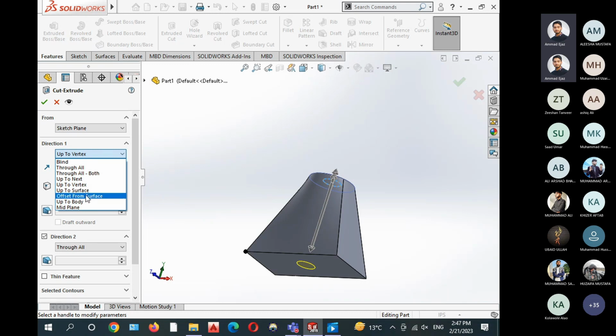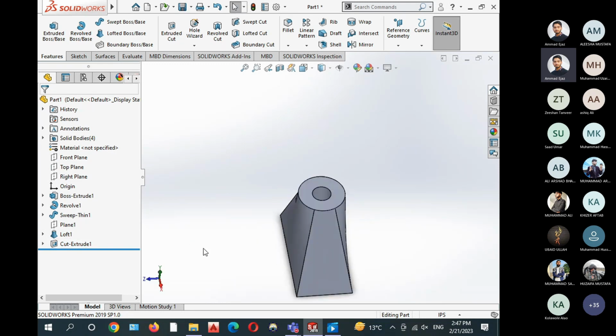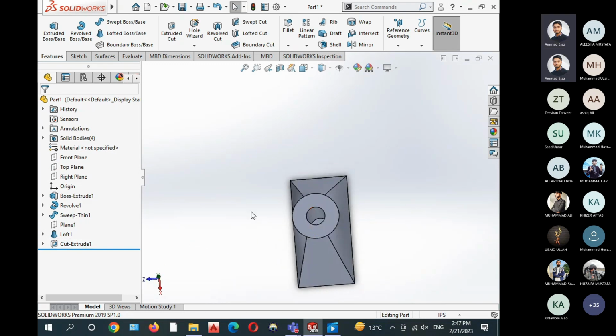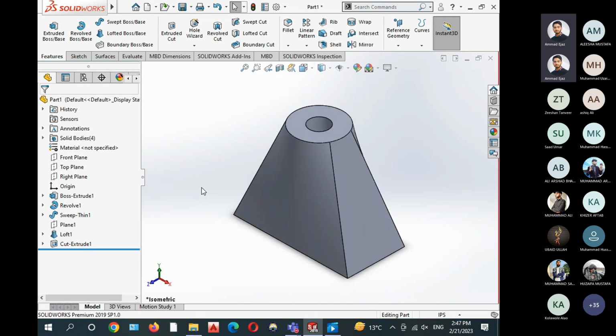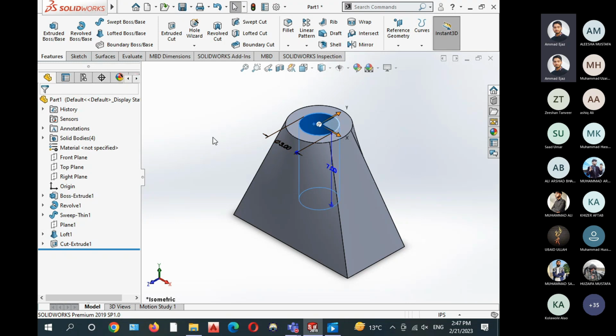You can also see other operations in here. These operations are exactly the same as the name denotes. Currently, it has created an extruded cut, a hole of about 7 inches in height and 2 inches in diameter. You can see in versions after 2016, if you select an operation, it will show the dimensions of this operation. Let's say I don't want this to be 2 inches in diameter. Just hit this dimension and create a 3 inches hole, and it will do the job for you.